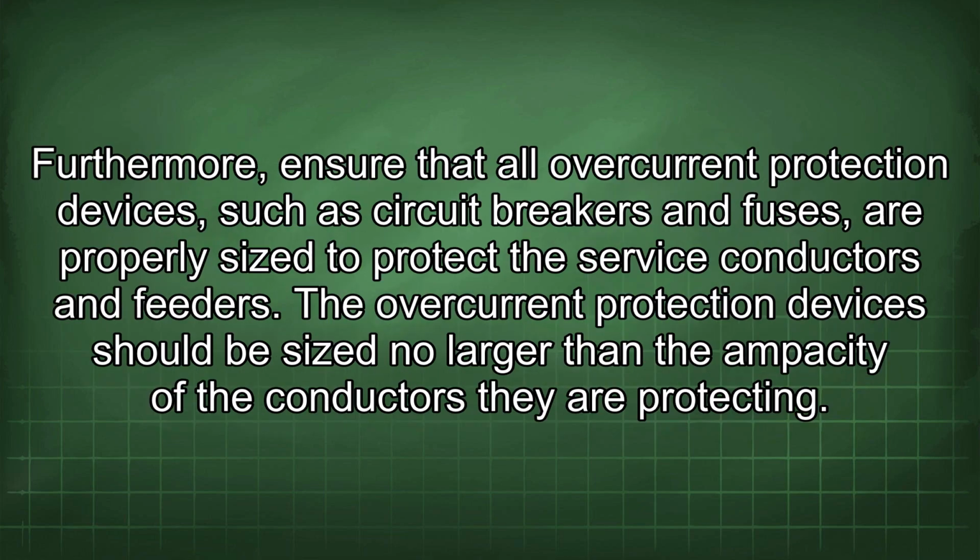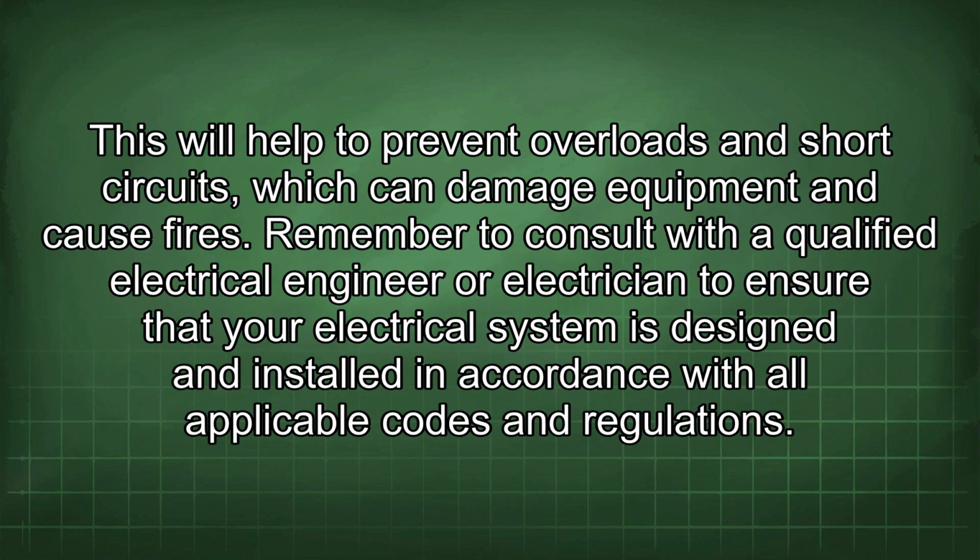Furthermore, ensure that all overcurrent protection devices, such as circuit breakers and fuses, are properly sized to protect the service conductors and feeders. The overcurrent protection devices should be sized no larger than the ampacity of the conductors they are protecting. This will help to prevent overloads and short circuits, which can damage equipment and cause fires. Remember to consult with a qualified electrical engineer or electrician to ensure that your electrical system is designed and installed in accordance with all applicable codes and regulations.